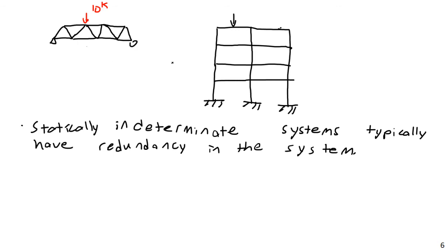Or if for some reason the truss was supporting an upward load instead of a downward load, then it would be the opposite. So basically, as long as the truss is in positive bending, then the top chord will be in compression, the bottom chord in tension.